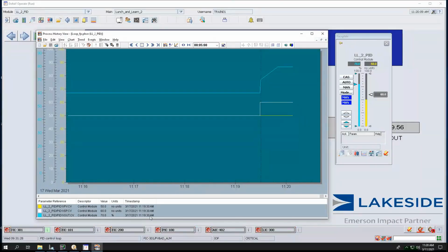So what I'm saying is that after 20 seconds, so at 11:19:50, if my math is gooder than my English, we should have reached 80%. And actually probably stopped it a little bit too short, but actually 11:19:50 is at 79.6. So you could see here that this part, the integral repeated the proportional part in the prescribed amount of time.